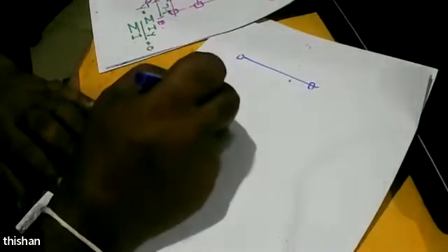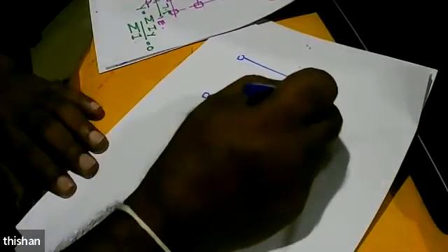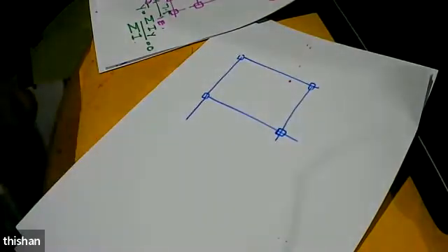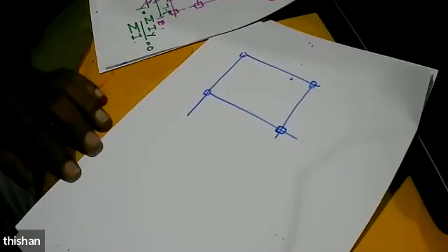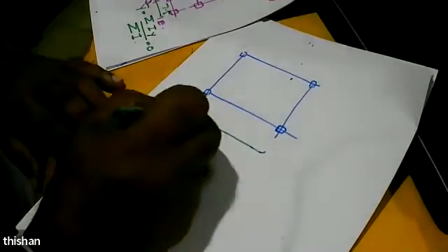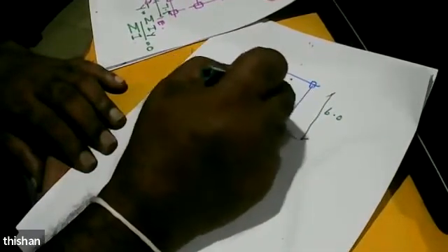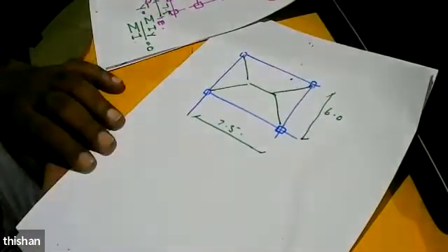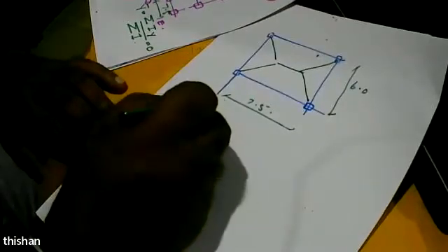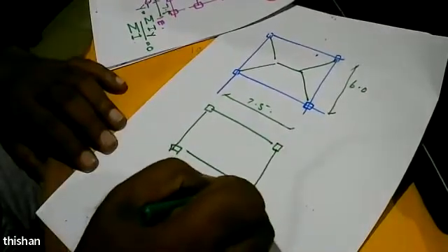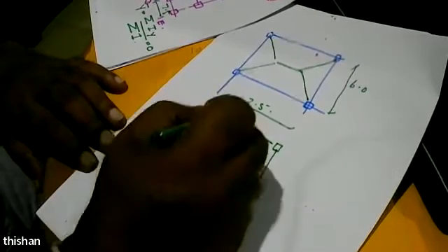So how do you apply the loads? You have one column here, here. So you get 7.5 meters, you get 6 meters. And according to Eurocode, they go for a simple load transfer like this. For a simple load transfer like this, BS 8110, if you want, you can use that also, because it gives a good set of tables that can be used.